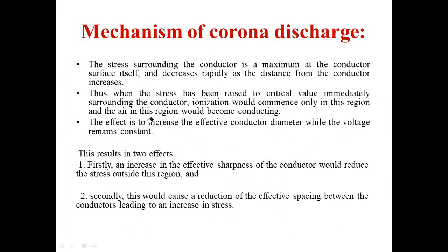Okay, so the closer the transmission lines are, the greater the chance of corona. That's when the stress has been raised to a critical value. Immediately surrounding the conductor, ionization would commence only in this region, and the air in this region would become conductive. The effect is to increase the effective conductor diameter while the voltage remains constant.